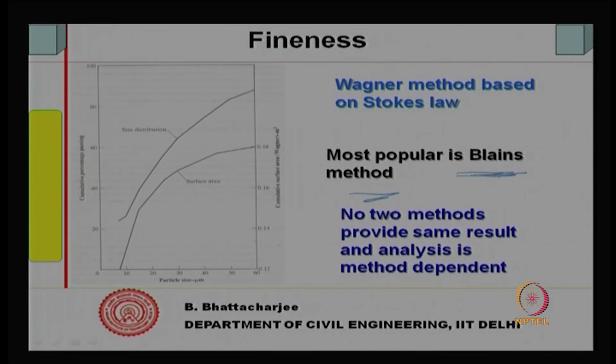this gives, but before that it is important to mention that no two methods provide the same result, and analysis is method dependent. Like time of transition, whatever particle size distribution it gives, laser diffraction does not give the same thing. Neither will the hydrometer analysis give you the same thing. If you do it through microscopy, it won't give the same thing.